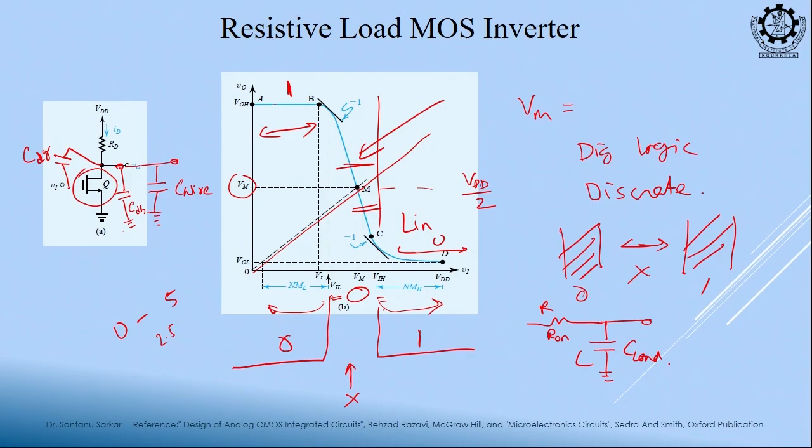Right. Similarly, if my switch is transitioning from 0 to 1, 1 to 0, this capacitor will be charged and discharged. So, some power dissipation will be going on, some power will be dropped as IR heat, right. This resistor will be heated up and some power loss will be happening.